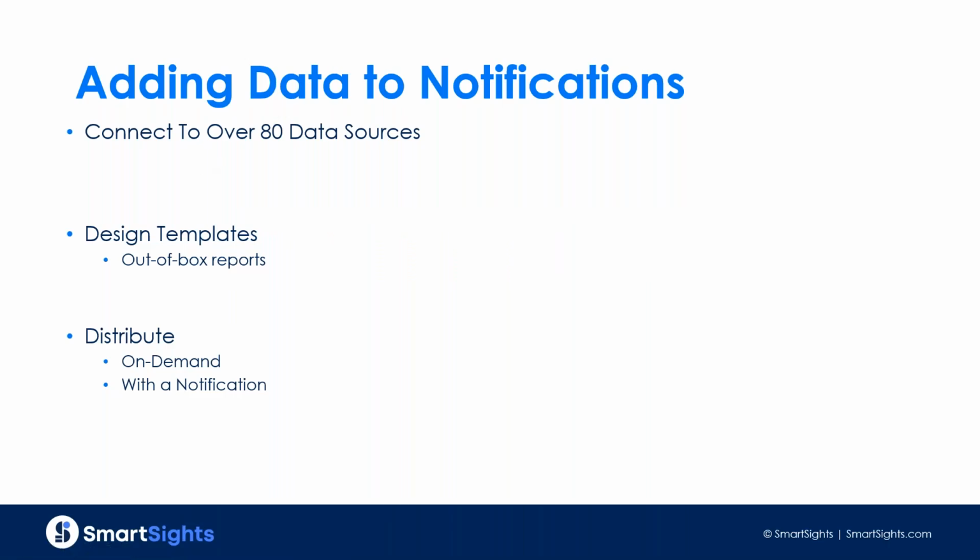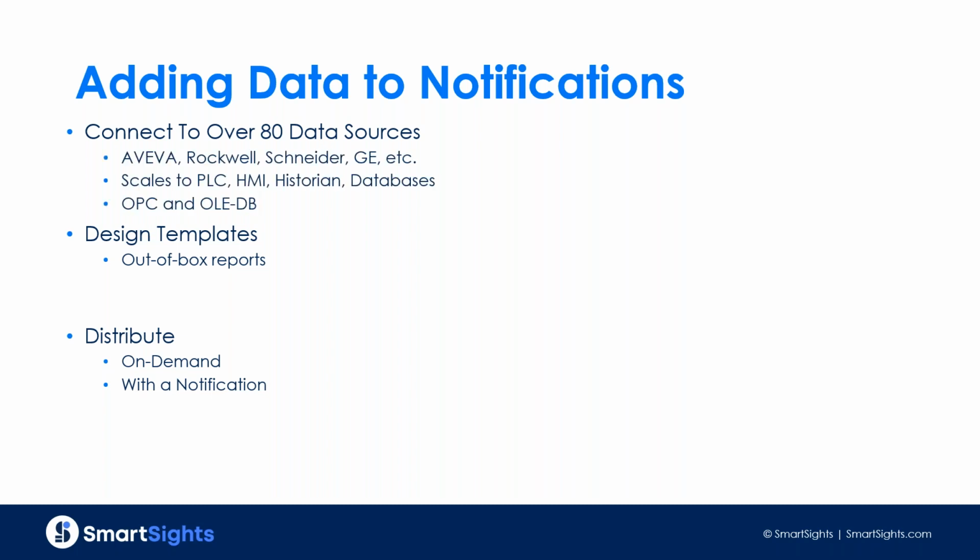And so how this works is when you add data notifications, it requires an Excel Reporter installation as part of that SmartSights bundle, and that system can connect to the in-plant data sources, right? We're talking about PLCs, HMI data logs, historians, relational databases. We support over 80 different data sources from all the leading HMI SCADA vendors that Win911 supports, as well as open standards like OPC, HDA, UA, HA, OLEDB, ODBC, and so on.